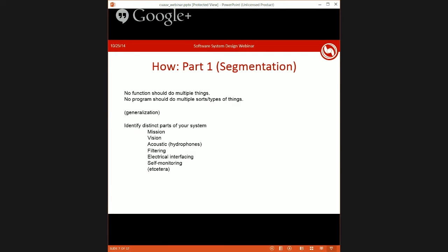And to this end, you want to identify at a high level, as you begin to split these up, what parts of your system are distinct and can be easily separated in this manner. Clearly, at least as CUAUV uses it, you generally have your mission system, which translates information about the world, usually in a filtered format, so where some object is, what tasks I've done already, how many points the tasks are worth, what the state of the submarine is, and what I know my capabilities are, into action, into what you want the submarine to do.